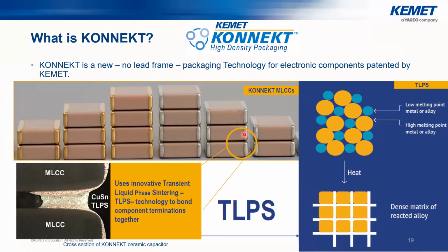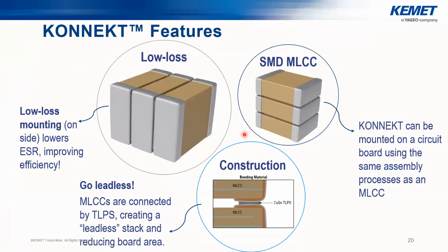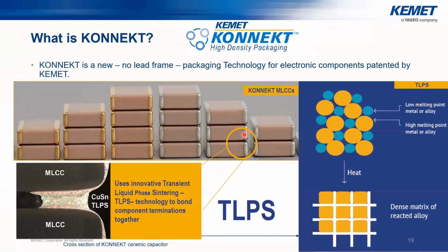So this kind of connection is a technology that we can apply on different types of ceramic capacitor. It does not depend on the type of the ceramic. It can be X7R or C0G. Different footprint as well. But today we have developed some standard values to help the user to select the right component for his application, and also to reduce the lead time of the production.